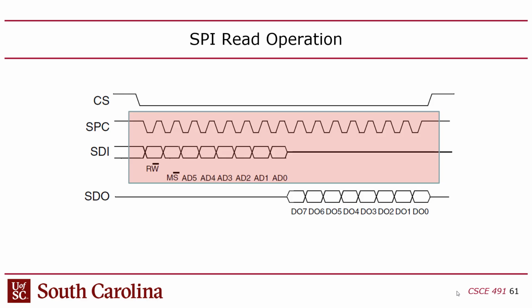Now, one thing I asked when I first saw this is, wait a second, there's an issue here. This thing doesn't have any flow control, because once I send the last bit of the address, the slave has one cycle to start sending the data back. That's not a lot of time. What if the latency of accessing this I/O register is more than a cycle? Yeah, then you're in trouble, because the master controls the clock, which determines the maximum latency by which the slave could start sending these bits back. So you have to stick to this, right?